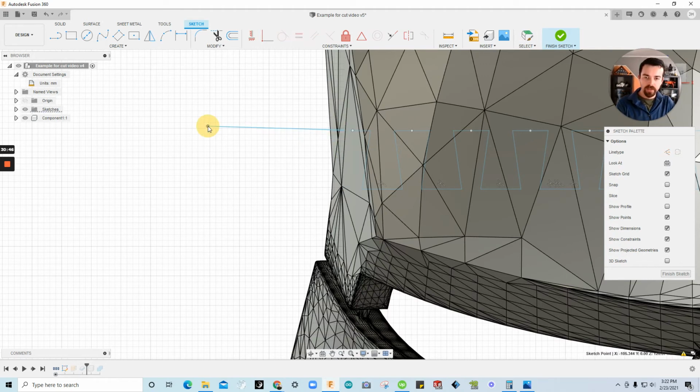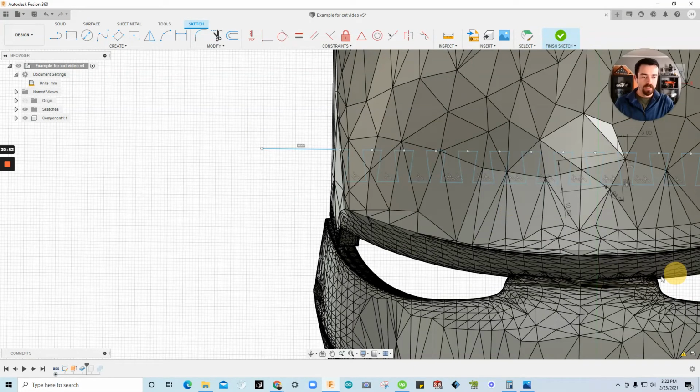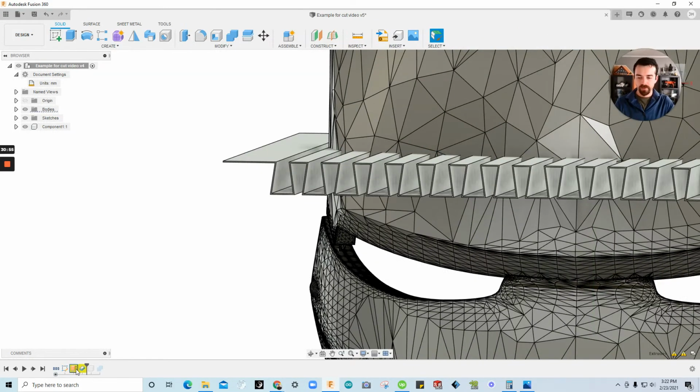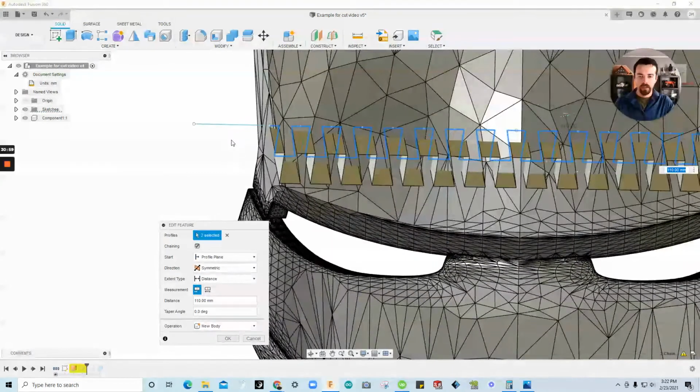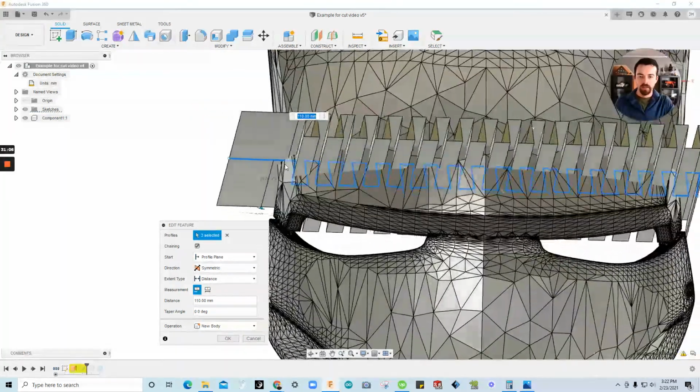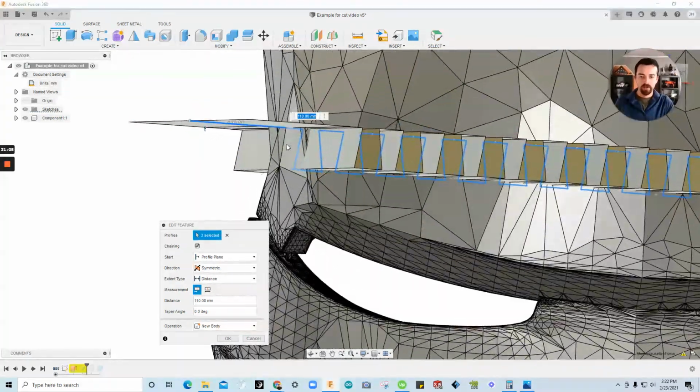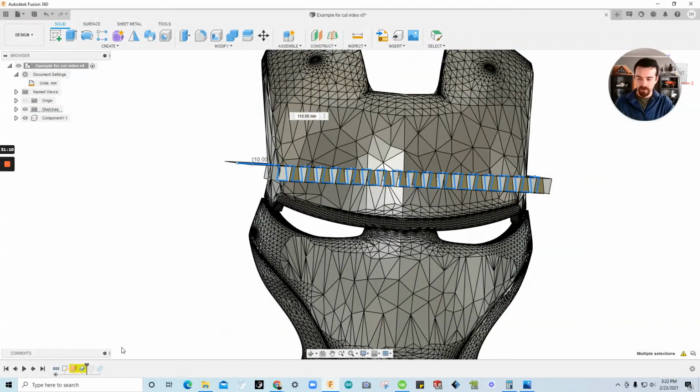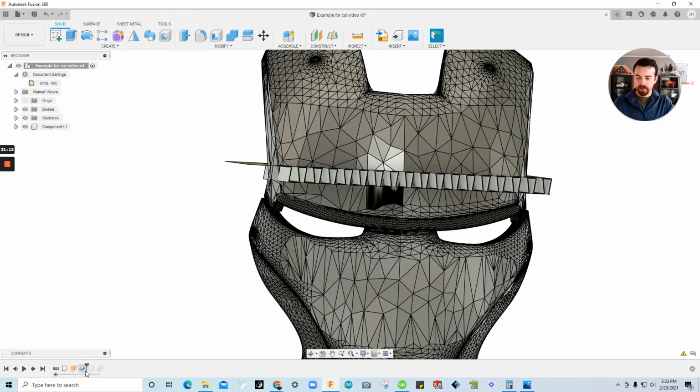This one's probably constrained. Nope, let me drag it. Oop, I don't want that. I want horizontal, etc. And finish sketch. Again, we have some problems, so we'll go ahead and right click, edit feature, and while clicking the select, we'll select the extra line we just drew to make a large long face to make that part, the last cut, a little bit bigger. Okay. Fixed everything. I'm going to go ahead and roll the timeline forward.